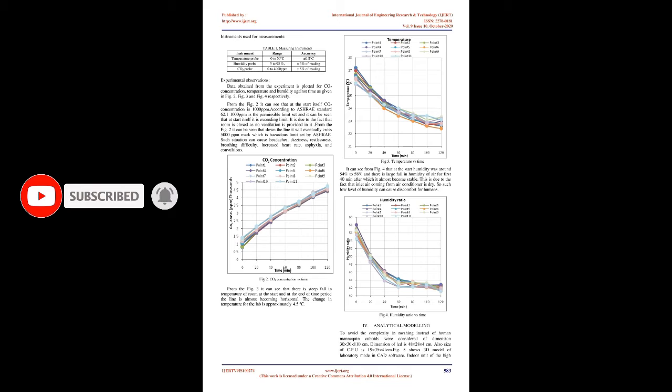There are 52 people sitting in the laboratory, each with 450 BTU/HR heat load. Also there are 52 CPUs and LCDs, each having a heat load of 65 W and 55 W respectively. Along with the above, there are 18 double batten tubes, each of 20 W.